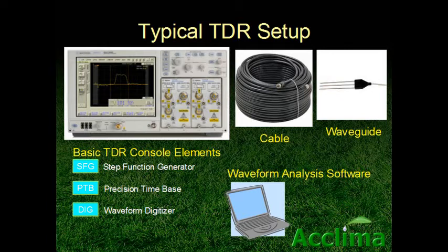But it also acts as a low-pass filter and removes much of the gigahertz spectral content out of the measurement, thus reducing resolution and possibly hiding important medium characteristics. Then, in addition to these, we need some software and a PC to interpret the waveform and derive permittivity and moisture content from it. We can improve this picture.